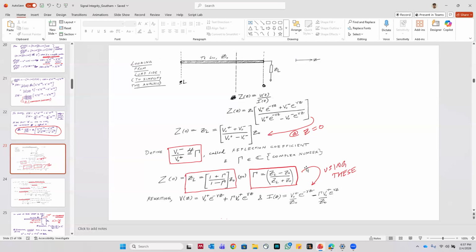Okay, and so if you have a situation where that reflection is too large, then what can happen is most of your signal gets reflected back and very little signal actually goes to your receiver side, right? And so what does that mean? That means that at the receiver side, your eye is starting to close because your signal strength is reducing because of the reflection, right? This is a very important concept. Everyone understands this, right? And you can always go back, do the derivation yourself and convince yourself that this is what the reflection coefficient is.